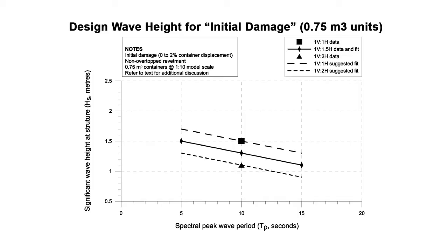We shift to a 10-second wave, so these are higher energy waves. The damage threshold drops to around about 1.3 metres. You can see very little damage, maybe 1% damage here, usually about 4 or 5% here. We shift to 15-second waves. These are high energy ocean swell waves, much more power in the waves. The threshold for no damage drops to about 1.2 metres. So in some circumstances we're getting quite high damage, 15%, which is failure of the structure once we get up here. So we set the design curves to this no damage threshold always.